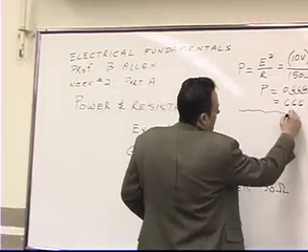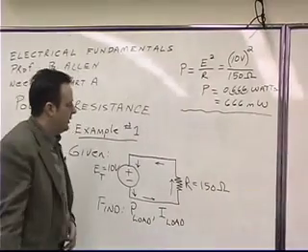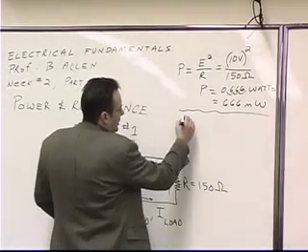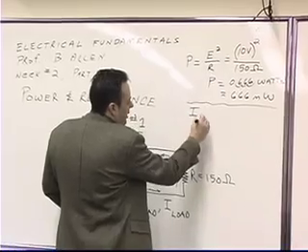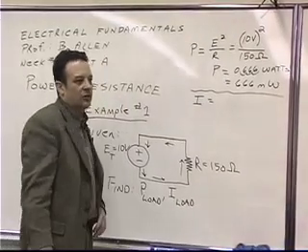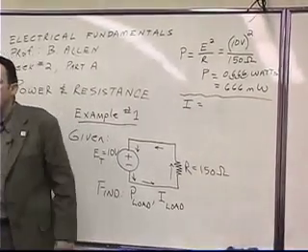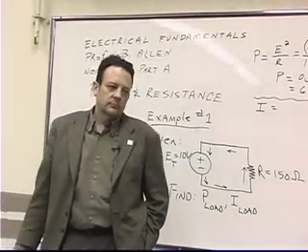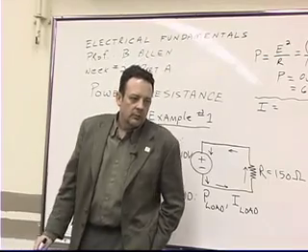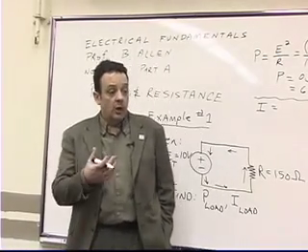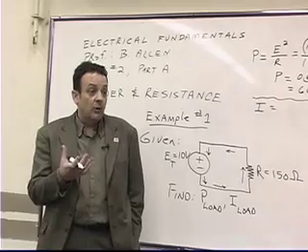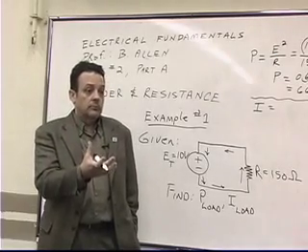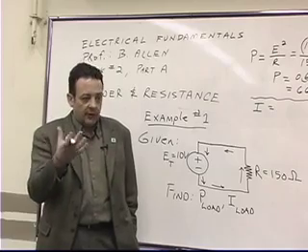All right. The second thing that we wanted to verify was how much current would be flowing in the circuit. Now, can anybody tell me why we would be concerned with how much current would be flowing in the circuit? Right, for your load, so your load would be beefy enough to be able to handle the current flowing through it, and the same thing for the wire. Both are the same, size of the wire.